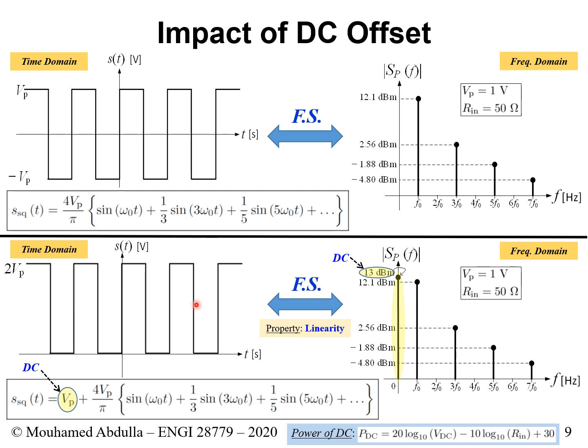A fourth way to know if you have a DC component is to look at the average. You look at your figure and simply average it just by looking at it. You say, okay, my signal goes from minus VP to VP, and it goes up and down. If I look at the average, what is the average voltage? Well, the average voltage is 0. So I know my DC component is 0. That's one very quick way to detect the DC component.